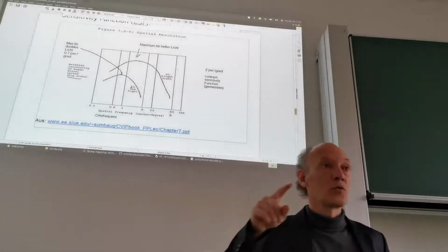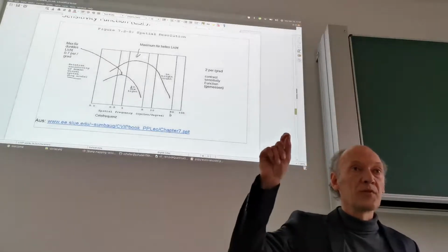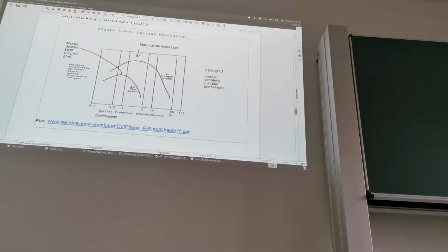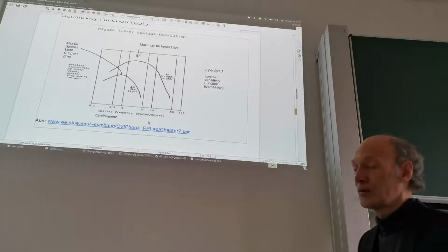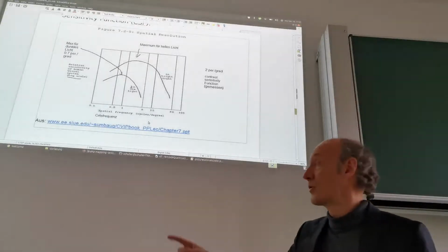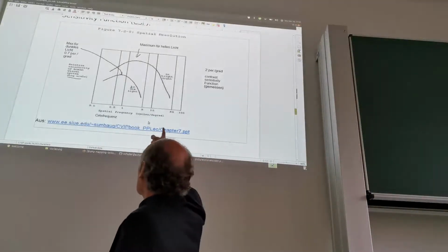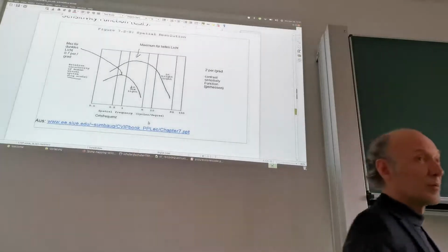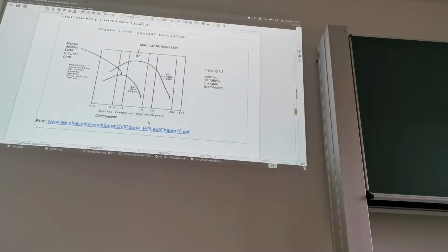So it means if the curve is higher, the eye becomes more sensitive, and we need to choose smaller quantization step sizes. And for the cycles per degree, we need to have some conversion to the subband index, right? So that we know the subband index is somewhere in this image. And this conversion, remember, depends on the resolution of our display and the viewing distance. So basically how many pixels per degree we can see.